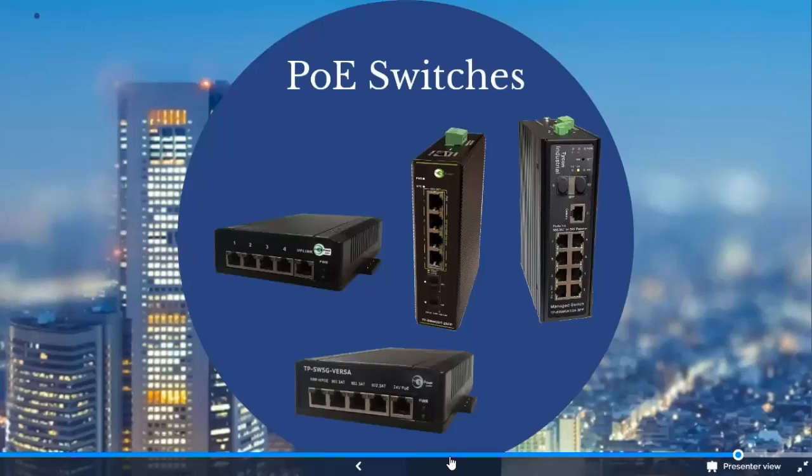The Versa switch on the bottom is also an unmanaged switch. It does require 48 volt, but you'll get 1 port at 24 volt PoE, 3 at 802.3 AT, or 30 watts per port, and then a 60 watt high PoE port. So very versatile. You're able to use with many different applications.